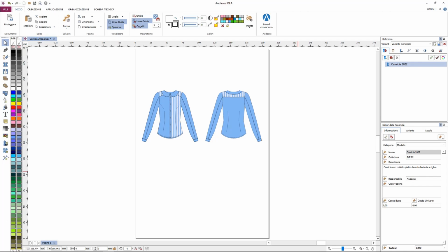We start inserting the first information on the model recorded during the file saving that we find in the property editor in the lower right part of the screen in a table. We are going to insert the table at the top of the page. On the left of the screen we are going to select the table icon. After clicking on it, this window will appear where we will choose the number of rows and columns needed. In this case 5 rows and 2 columns.